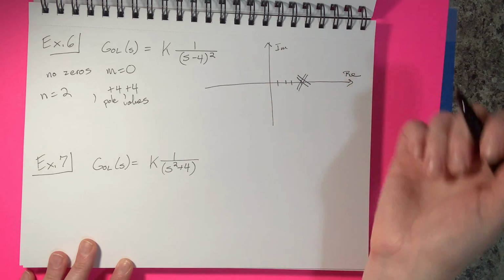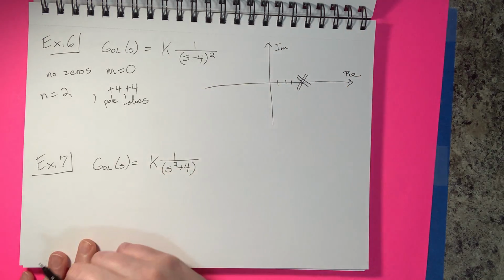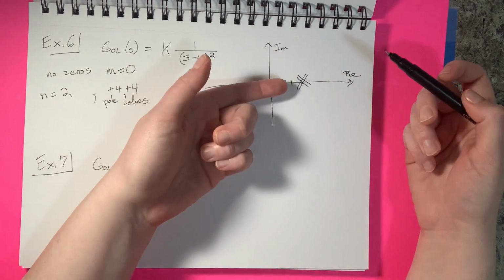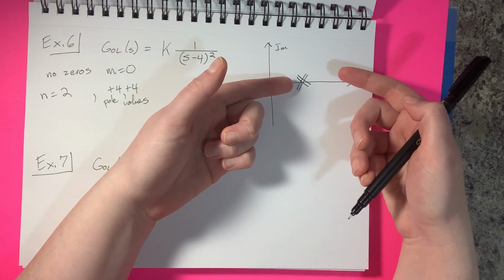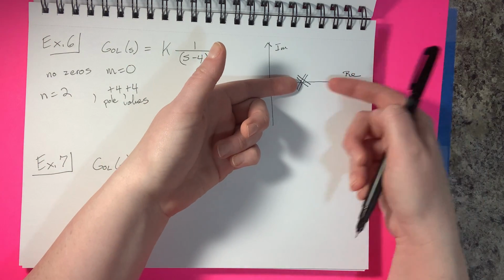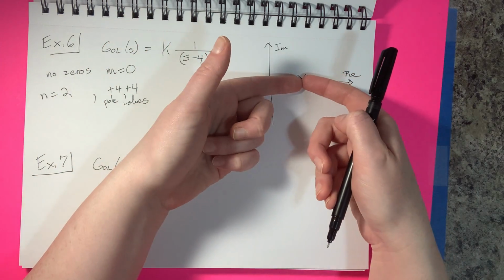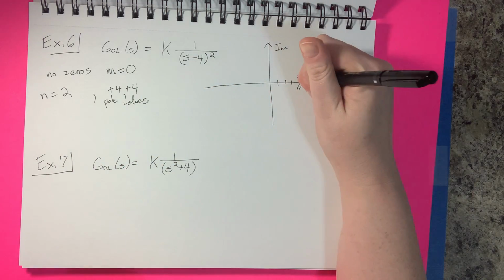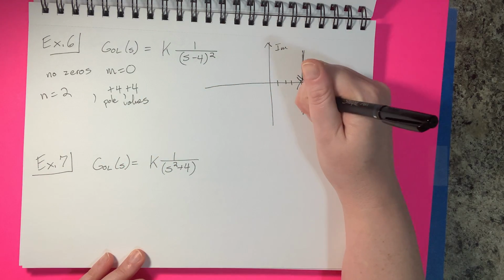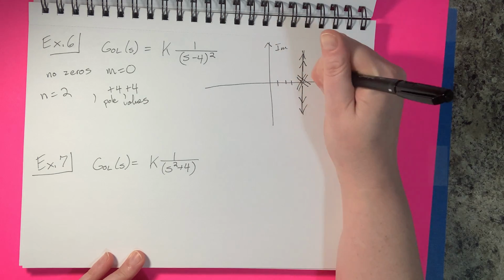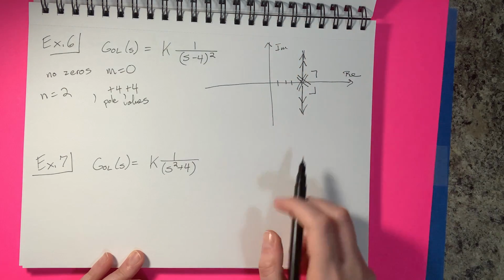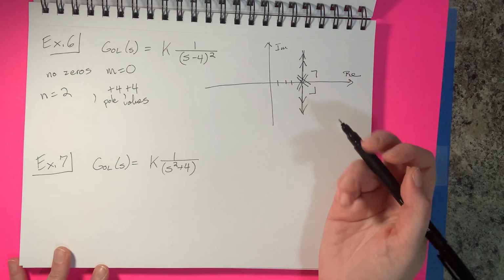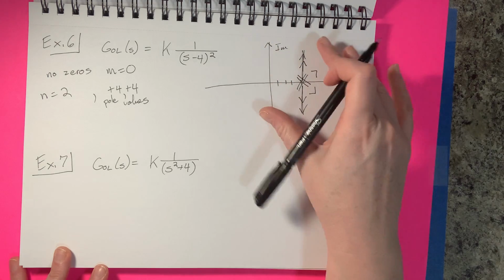Okay. In this case, what we would need to use is our collision rule. So they're actually on the same value, but the result would be the same as if we had a +3, or actually even a -3, and a +5. And they move out here towards each other, and then they would collide off. But these two just happen to already be at the value that they'll collide off of. So what's going to happen is they will move towards ±90-degree values from the real axis, okay? All right, and so that would actually complete your locus.